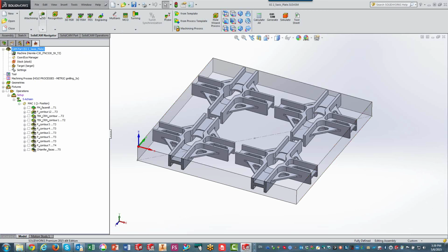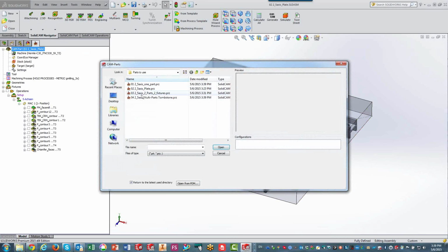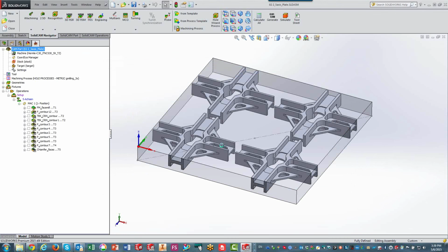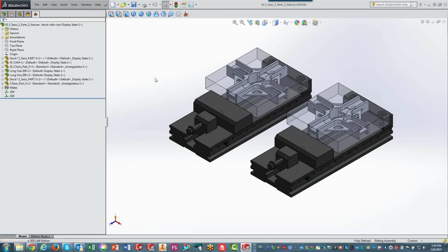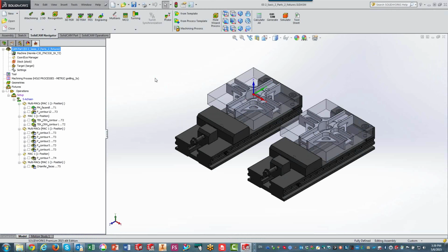So you've seen the option of combining coordinate systems, in this particular case, using rotate together with matrix. We've also seen the option of what happens if I'm using the same part, but on 2 different fixtures, where we showed 2 options. One was combining the rotate together with transform list, and the other one, which is more advanced, using the option of rotate together with transform via coordinate system, which is extremely helpful in many cases, making it a lot easier actually to work, especially when operations come back at a later date.